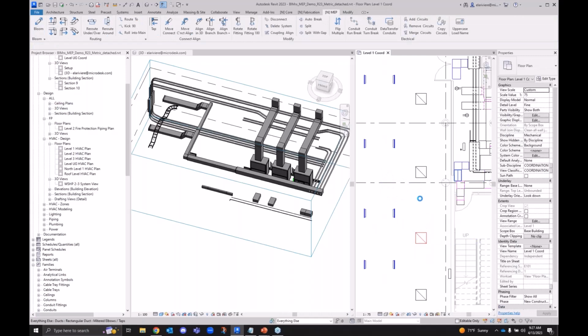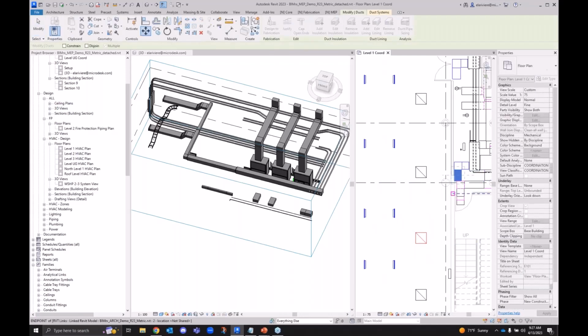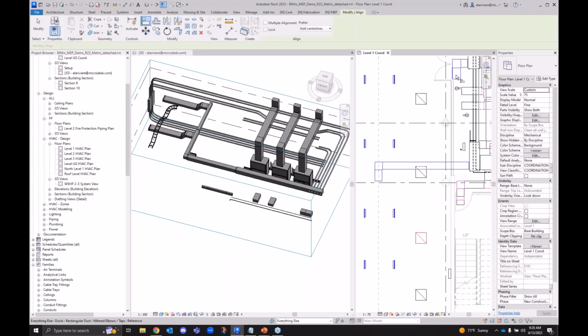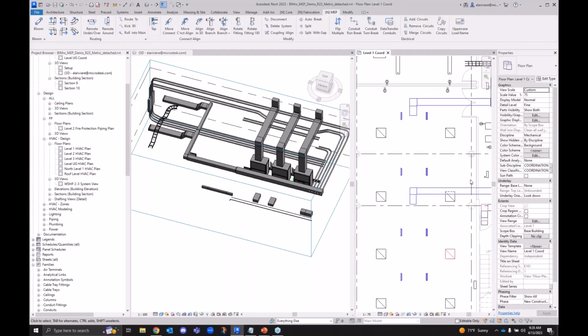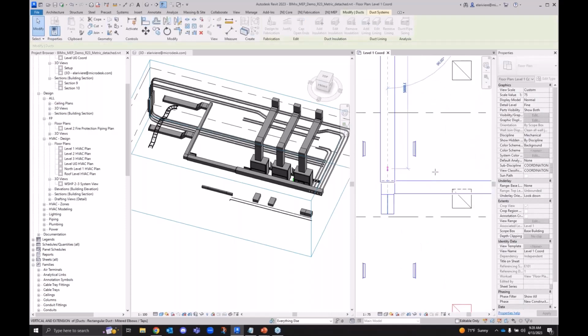Just use the move command to make it extra easy. Move one of these over towards the middle there. I can do a real quick align to get the second one in the same space. And maybe we want to extend these things down just past. Don't forget that little trim extend that I've been using this whole time can always be used to extend an element down. So frequently I'm using other elements that don't even relate to help extend these things and move them around.